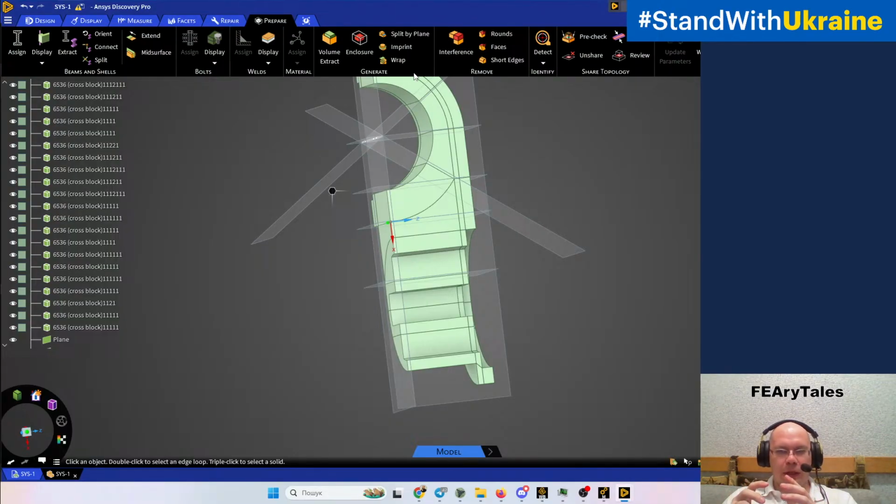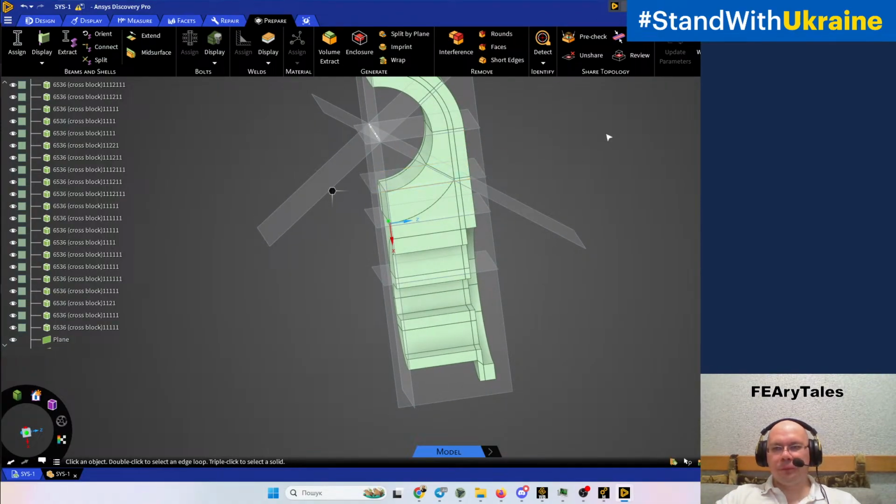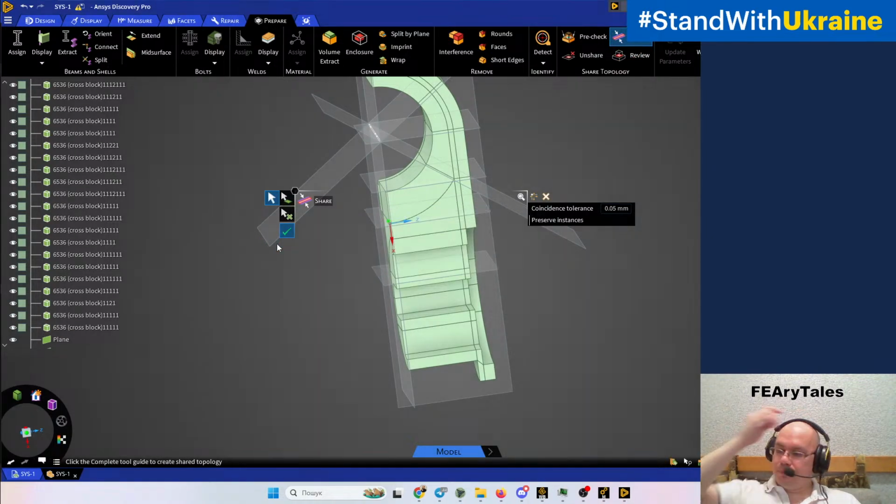We need to create a mesh where every object has the same number of nodes on the edge and the same pattern of elements on the faces. So we can create either margin nodes or something else to produce the good mesh. It needs some additional time. It's not very difficult when we create the fully hexa mesh. So we will stop here and come to another part.